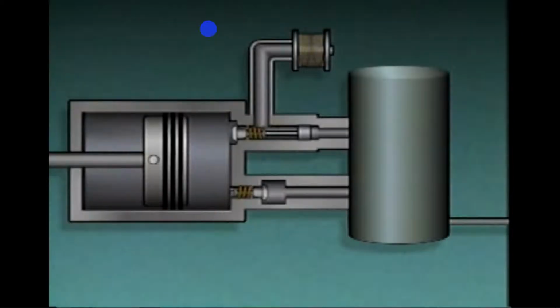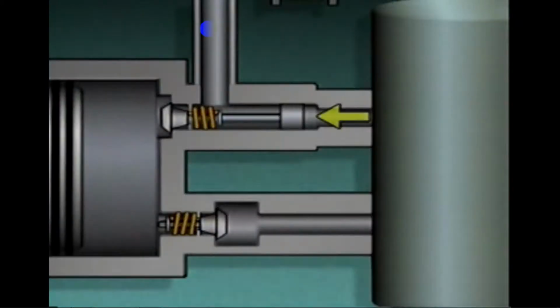This is a simplified illustration of a portion of a compressor system that uses an inlet valve unloader. The unloader consists of a piston and a connecting rod, which is connected to the inlet valve on the compressor. A pressure sensing line is connected from the unloader to the receiver. Gas from the receiver fills the pressure sensing line. As the pressure in the receiver increases, it moves the piston and the connecting rod and opens the compressor's inlet valve.